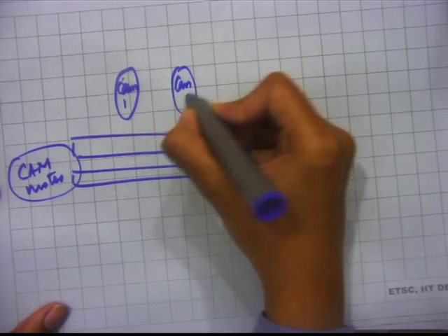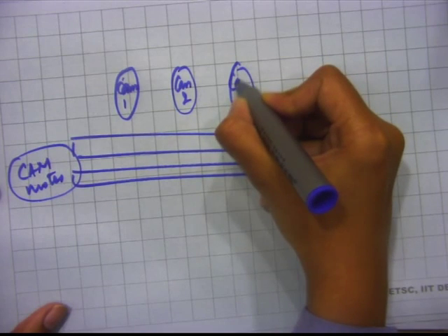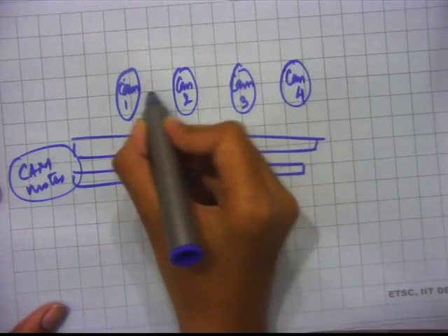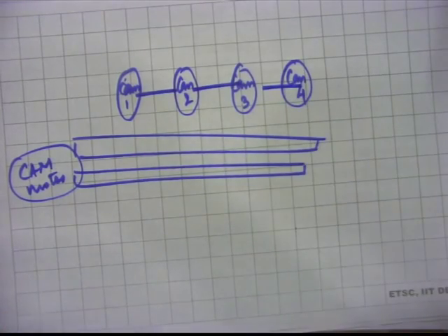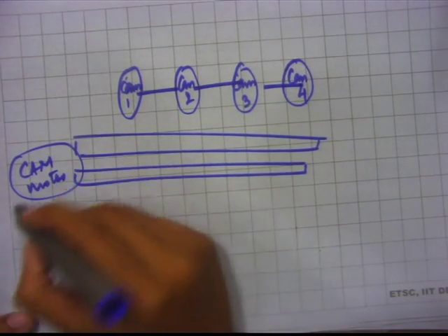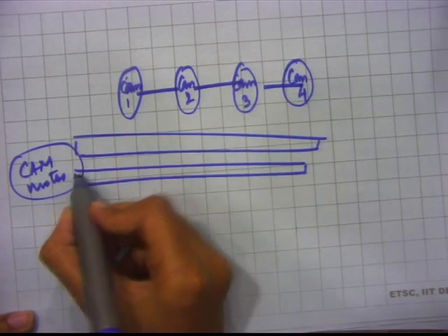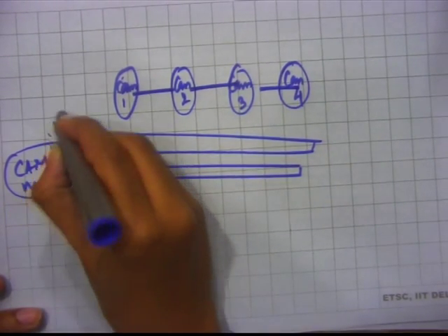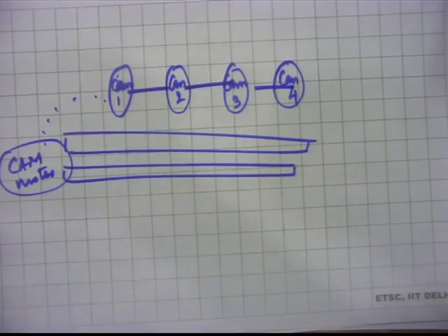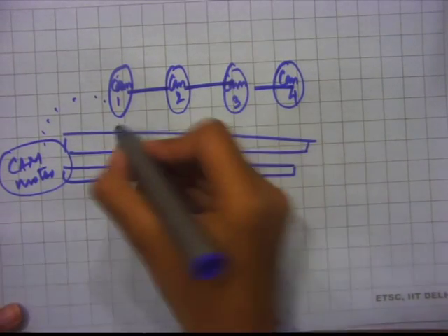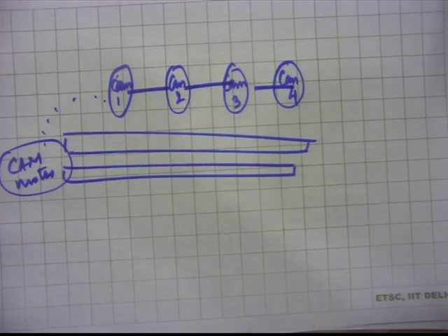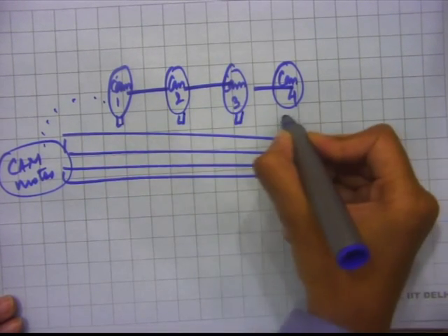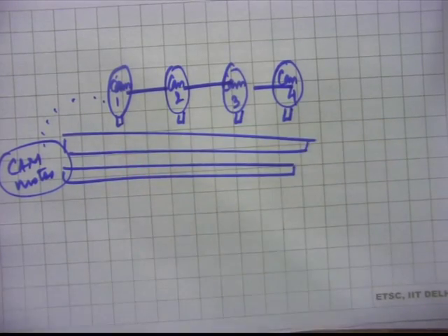We have 4 pick and place modules, so we have 4 of these cams. Now these cams are connected mechanically, right? And the main cam motor drives these cams through the encoder and all those belt mechanisms. So it's kind of driving these cams, and these cams are doing the pick and place. All of these have the pneumatics attached to them, the cylinders which do the pick and place.